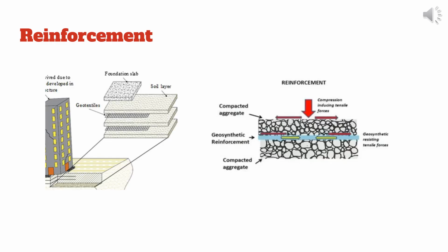The soil is sandwiched between several layers of geotextiles, so the size and construction cost for concrete foundations can be reduced, while buildings can sustain much larger earthquakes without collapse. The geotextile grids are so strong that when you apply pressure, they won't break down. However, they can deform, making them suitable for buildings in earthquake areas.